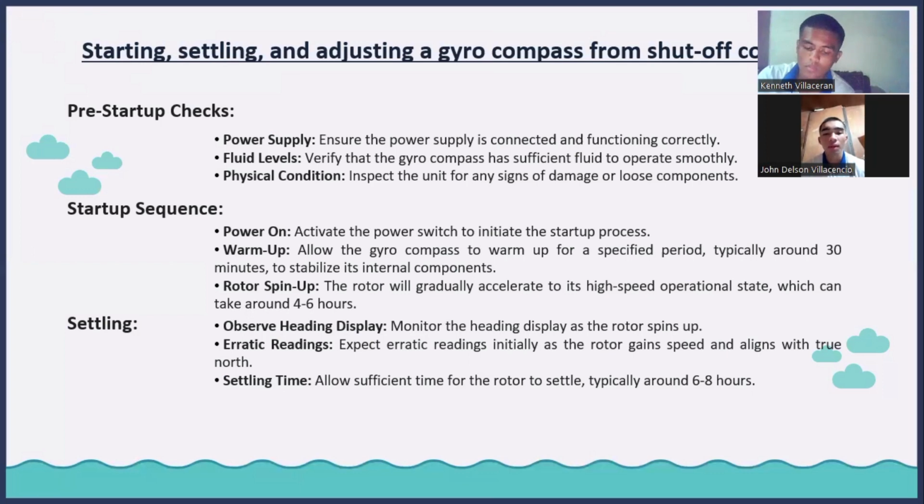Observe heading display. Monitor the heading display as the rotor spins up. Erratic readings initially, as the rotor gradually aligns with true north. Settling time. Allow sufficient time for the rotor to settle, typically around 6 to 8 hours.